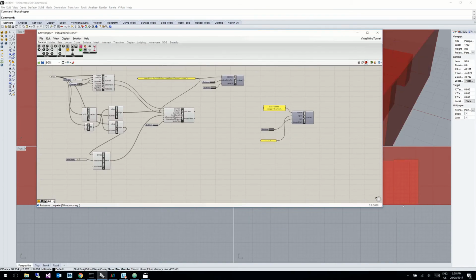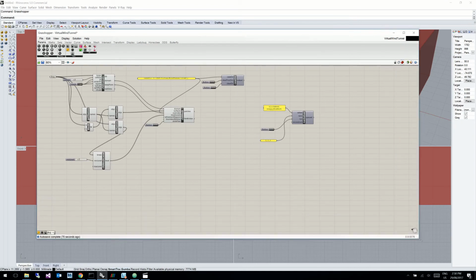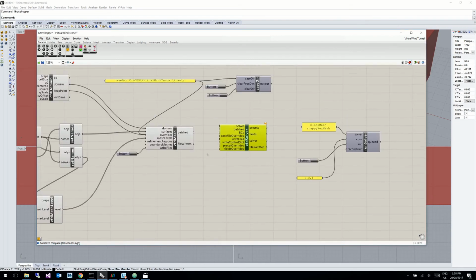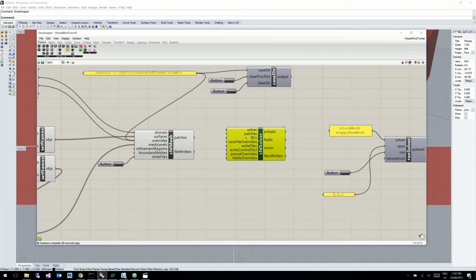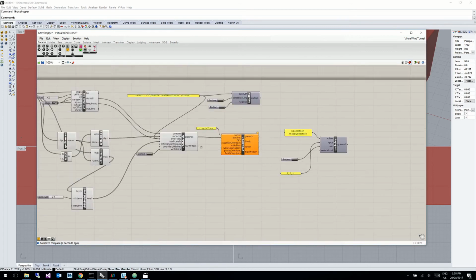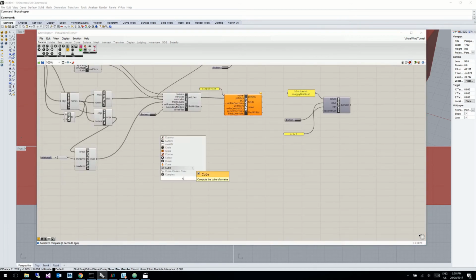So now that we've got an okay looking mesh, we'll set up the rest of the case, including the boundary conditions and the solver. So we'll add a CFD solver component, and this will actually add in all of the remaining files, such as boundary conditions and everything that's required to actually run an actual solution. We define a solver. In this case we'll use SimpleFoam. The patches are the same as what came out of the mesh. Now we need to add some boundary conditions.